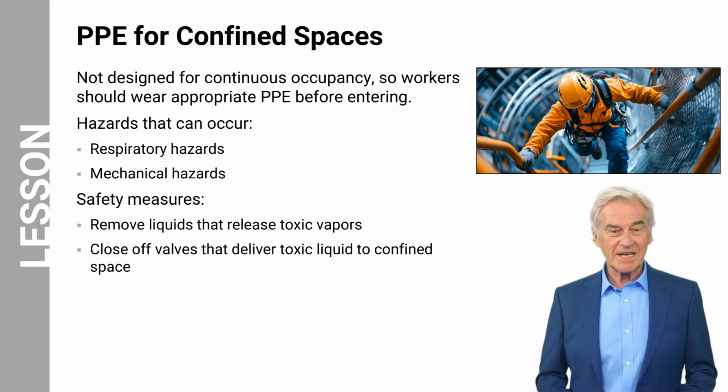Safety measures that should be taken before entering a confined space are to remove any liquid from the confined space, particularly ones that release toxic vapors, and close off all valves that could deliver toxic liquid to the confined space.